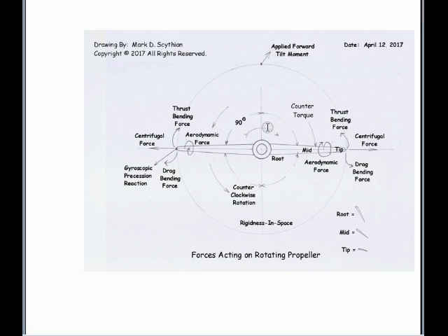So anything that rotates, whether it's aerodynamic applications or not, whether it is a rotating disc or a rotating flywheel or a rotating sphere or a BB gun round, the rotating ball bearing, it will always have centrifugal force wanting to pull the material out from its center of rotation equally on each half section outward on the rotating plane due to centrifugal force. Whether it be a flywheel rotating, it's going to have centrifugal force wanting to pull the flywheel plate apart, and that's why the materials are reinforced for that.